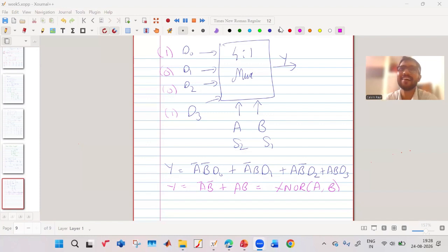But from what I've heard and seen at IIT Kharagpur, from the few people I've met, they first think of the application of their circuit. Based on that, they make a schematic, size the transistors and run simulations. After extensive simulation, they start from an ideal block, slowly make it more practical, and fine tune it. Then they run corner simulations.